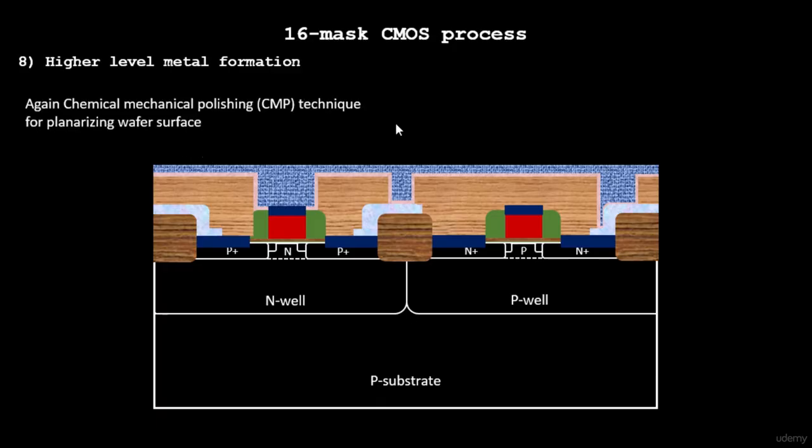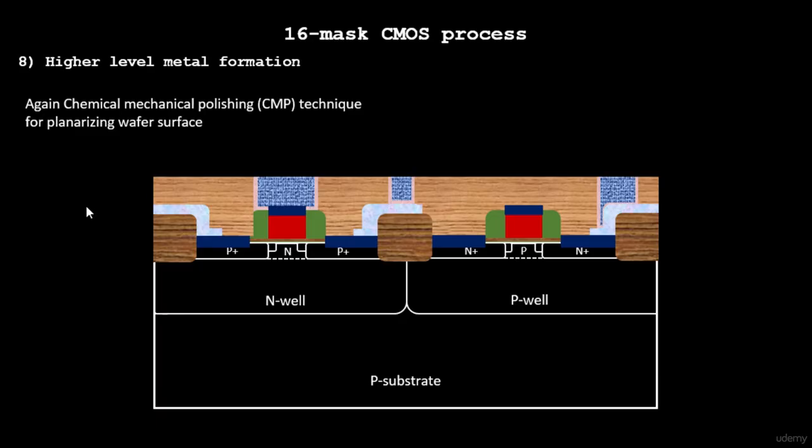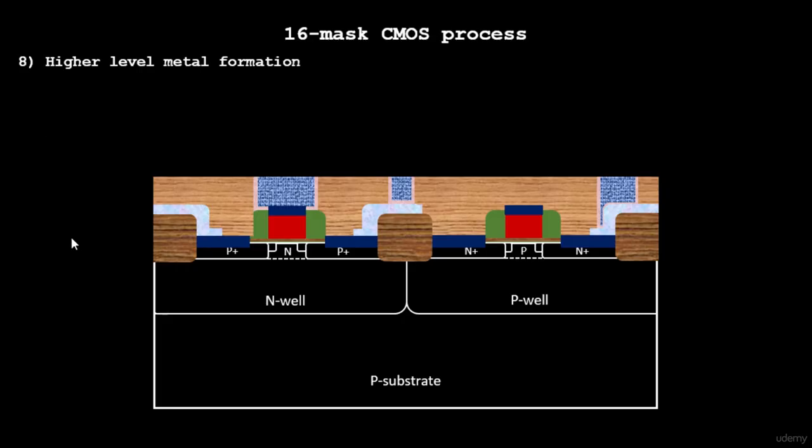These are low resistance contacts. So now if you see the poly contacts and the contacts present over here, they are all being made now. Let me take you to the previous figure. Previously it was like this. Now the titanium over here, and the titanium over here, whichever are in contact with the silicon, react with silicon to form TiSi2. TiSi2 is a low resistance metal which can be used for your local interconnects.